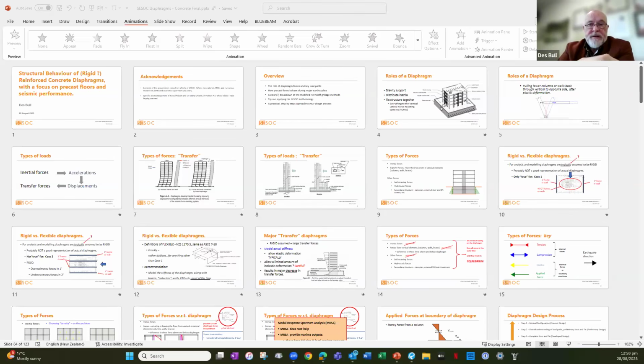What we do know, and this goes back to Debbie Gardner's, now Mrs. Shearer, Dr. Debbie Shearer's PhD, was if you include tension in your concrete, you get a totally different distribution of forces. It's actually quite helpful. Things are less stressful, less harsh. But what we don't know is we can't predict when the cracks are going to occur, how far, what the extent of the crack, what the loss of stiffness is.